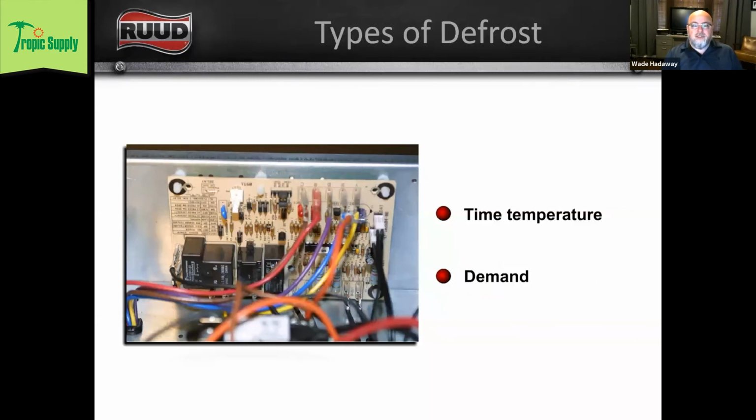So there's really two types of defrost. There's time temperature, which we're really not going to go into very much, but that is a very old school way of going into defrost. And then there's demand defrost, and all modern heat pumps really use demand defrost.